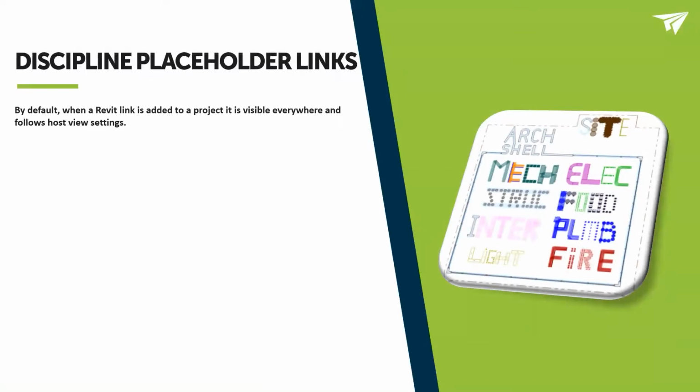By default, this is just common knowledge, this isn't something specific to the pack, but by default, when Revit links are added into a project, they're visible everywhere and they follow the host view settings.